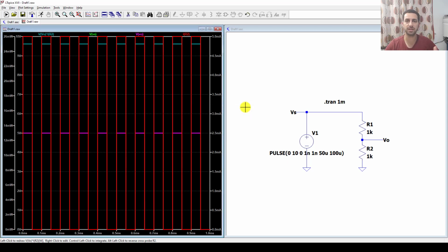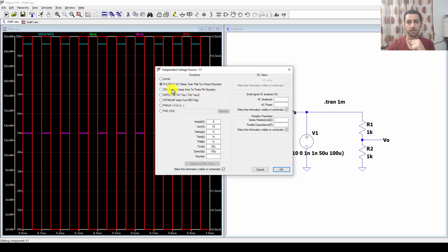It made the integration, as we learned in power electronics lectures, that the average power is the integration of the instantaneous power over a cycle. Okay, and we have 10 cycles here. LTSpice can recognize that and measure the average value. Okay, so this is the thing that you have to duplicate now before going to the next step. So let's now go to a different type of waveform.